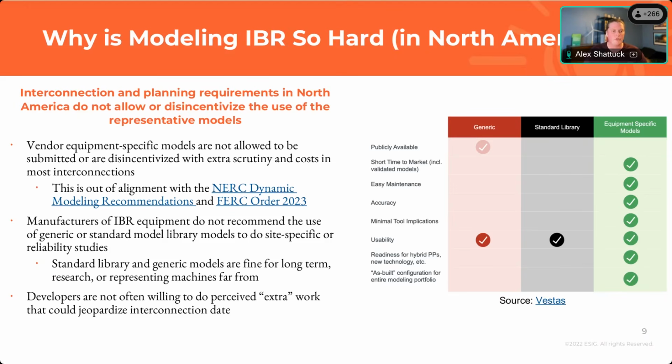Many or almost all manufacturers of inverter-based resource equipment don't recommend the use of generic standard library models to do site-specific or reliability studies. They just don't have the accuracy or detail or fidelity necessary to actually represent a specific type of technology. If I'm doing research or long-term planning, or if there's a machine far from my study area, or the manufacturer's gone out of business, standard library models and generic models are fine for those types of things because there's no other choice.